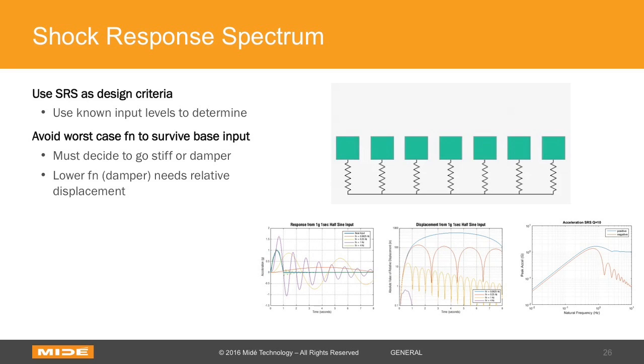As you see, the higher frequency 4 hertz spring really tracks the input acceleration pretty well, whereas the lower frequency ones actually dampen out the vibration levels. Some of the springs that have natural frequencies around bad areas to be, like the 1 hertz, are amplifying the input. The input's only a 1G, 1 second sine pulse, but you're actually getting nearly 2 Gs for certain frequencies.